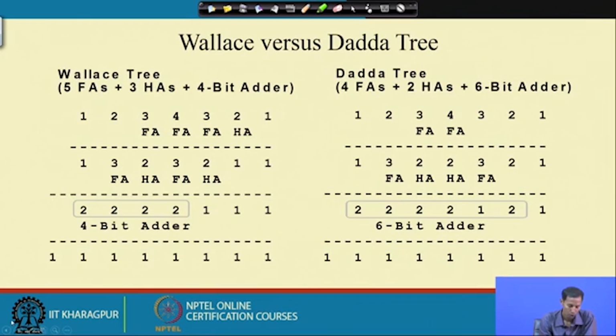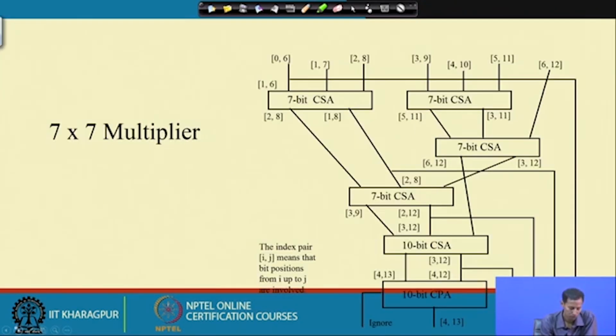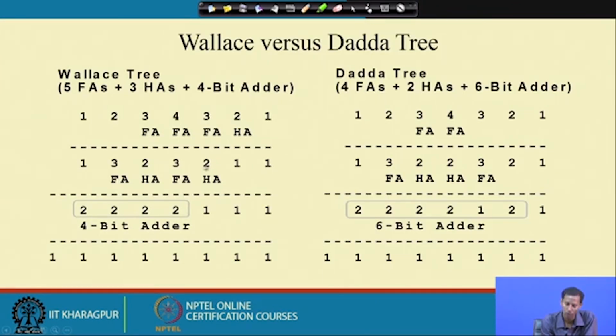Okay. So, then after that I have to use one half adder for this 2, full adder for this 3, half adder for this 2, full adder for this 3. Okay. So, once again I consume this half adder. So, this will produce 1, this 3, that 1 and carry from this, so it requires 2.